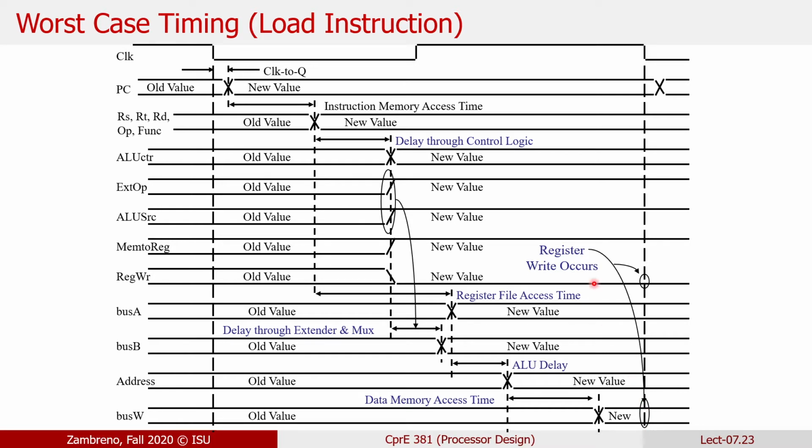We don't see this view of timing when we are doing our ModelSim simulation. We could have. We could have built these components with delays associated with them. That's a relatively straightforward thing to do in VHDL. And then you would see a version that has basically a lot of incorrect results being calculated, right? The ALU output is only being shown as being valid at this part of the cycle, but it actually has some output throughout.